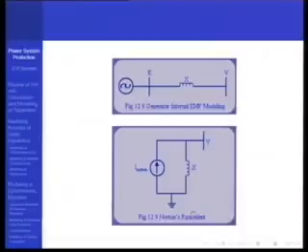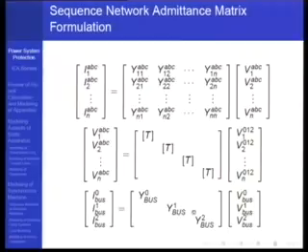Yeah. So what we do here is to calculate the Z bus, from where we get the Thevenin's impedance, and from that we calculate the fault current. Suppose I want the Thevenin's impedance at bus I, zero sequence value suppose. Then I will take this matrix equation, I bus 0 is equal to Y bus 0 into V bus 0, and I will inject a current of 1 ampere or 1 per unit, because this may be all in per unit. So 1 per unit at bus I and 0 current everywhere else.